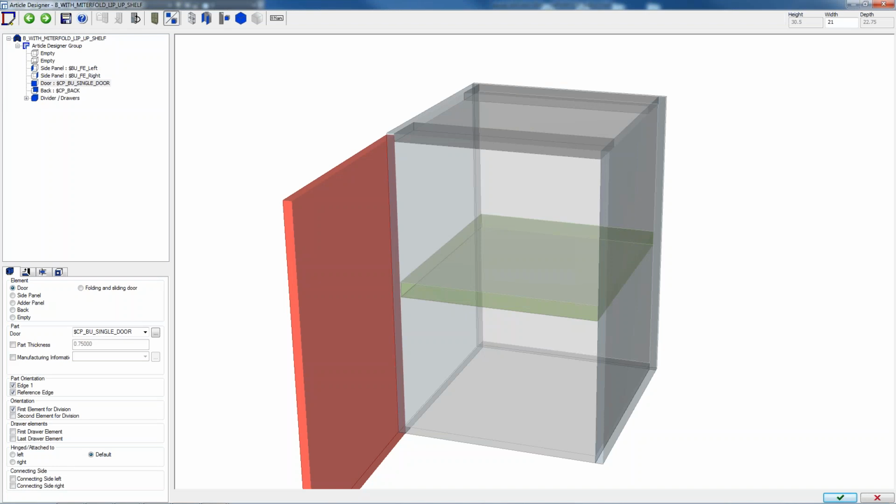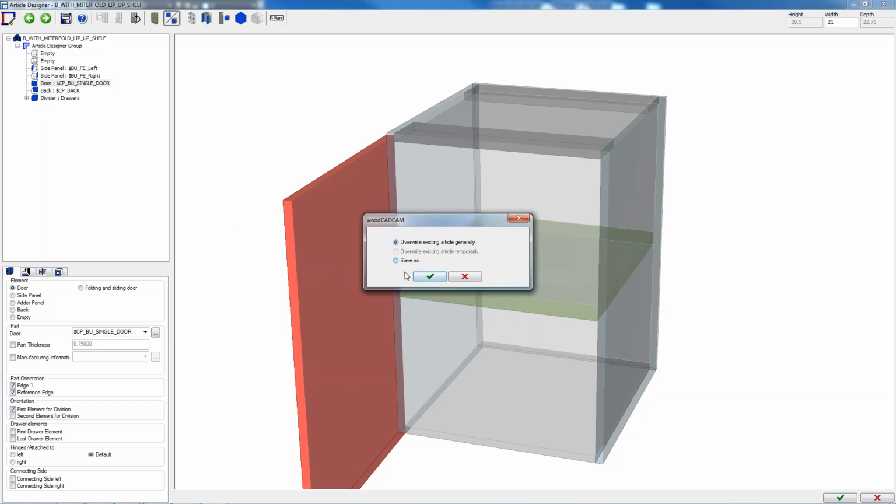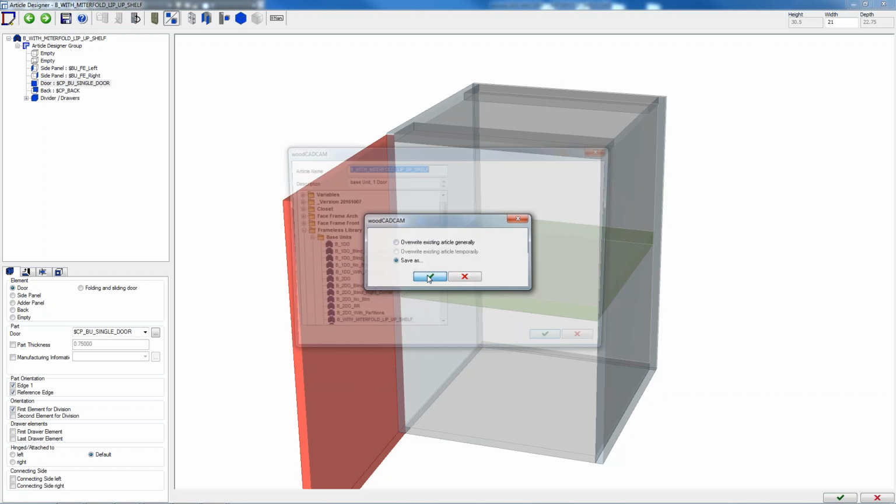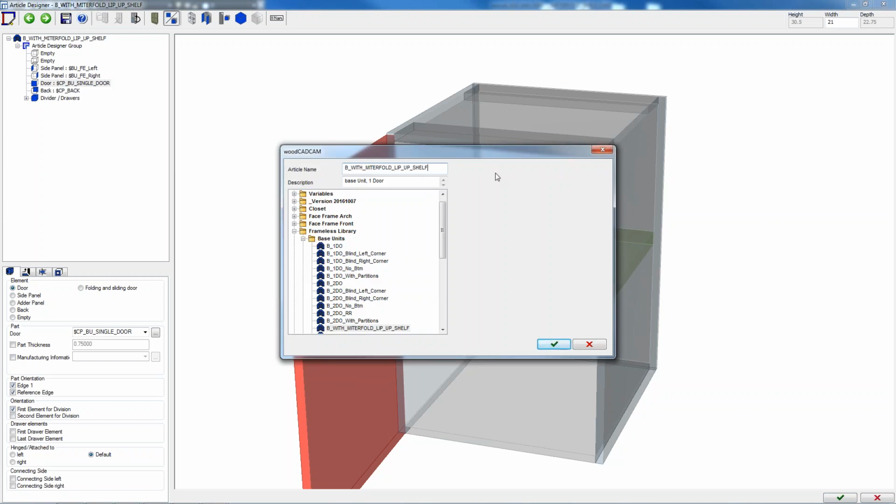There's another suggestion to go over how to modify gaps or reveals between doors, drawers, basically fronts. I know that we set up our 332nds, but how to manually override them. Okay, no problem. So once you're ready, drop the cabinet and tell me what you want to do.